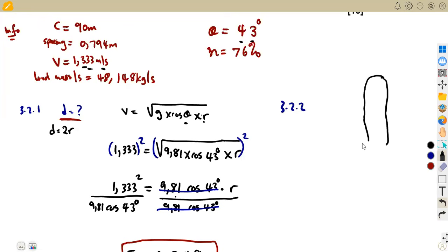All right, so this is the layout of our chain, whereby you are to consider here a circular part and also here a circular part. So what it means is the chain is being affected by a half circle on top here. It's covering a half circle on top, and also a half circle below. Remember, the perimeter of a circle is 2 pi r. But now you are considering half of a circle, so it's going to be pi r, which is the length from this point to this point. The length of that semicircle is going to be pi r. On this side it's going to be pi r.